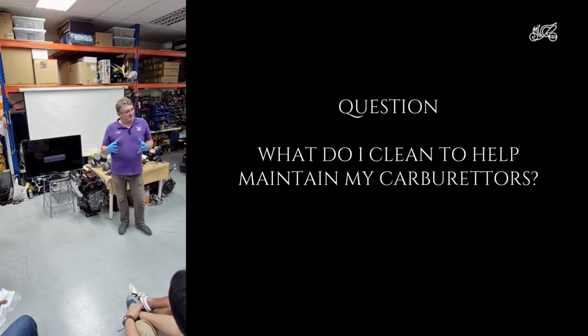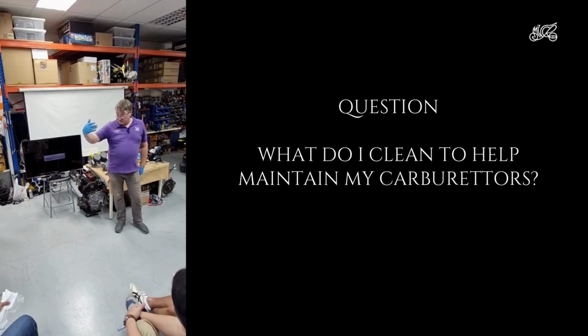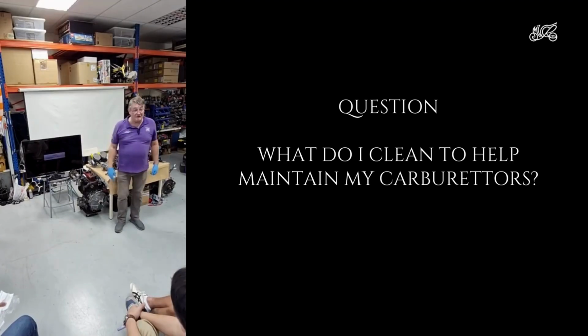The fuel. Fuel is a pretty cheap thing. If you look at it from an industrial perspective, fuel is just the cheapest fractions out of a distillation process, which they can sell to the general public. So it's not pure octane; it's a whole mixture of anything they have, and it's not necessarily very clean. And so, as it's evaporating in the airstream, some of the garbage doesn't evaporate and stays in the carburetor, and that builds up and eventually causes trouble. And these solvents dissolve all that garbage and suck it through the engine and out the exhaust.